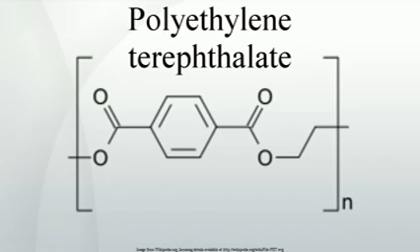The particle size distribution of impurities is very wide. The big particles of 60 to 1000 µm, which are visible by naked eye and easy to filter, represent the lesser evil, since their total surface is relatively small and the degradation speed is therefore lower. The influence of the microscopic particles, which, because they are many, increase the frequency of defects in the polymer, is comparably bigger. The motto, "What the eye does not see the heart cannot grieve over," is considered to be very important in many recycling processes. Therefore, besides efficient sorting, the removal of visible impurity particles by melt filtration processes plays a particular